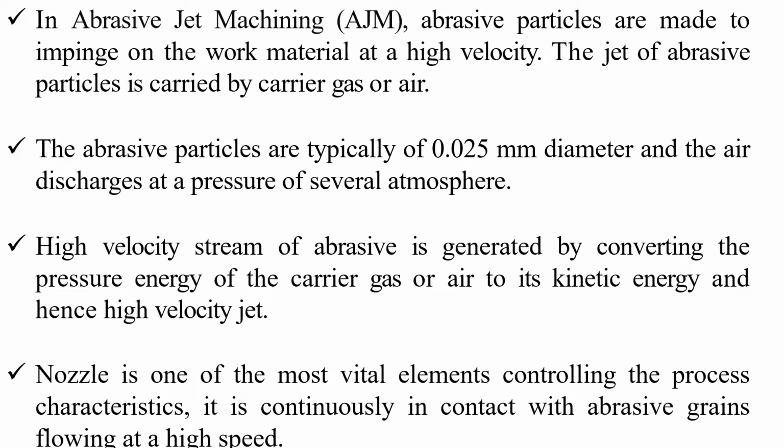A high velocity stream of abrasive is generated by converting the pressure energy of the carrier gas or air to its kinetic energy, and hence the high velocity jet. The nozzle is one of the most vital elements controlling the process characteristics. It is continuously in contact with abrasive grains flowing at a high speed.